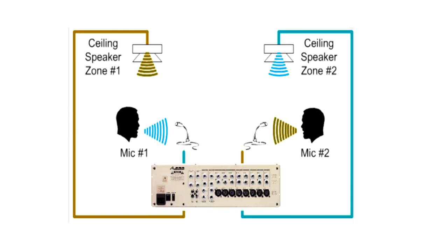But they have a microphone right next to them. Well, you don't want the audio from that speaker going to that microphone causing feedback. And so for that person that's sitting at a location with a microphone right next to a speaker, you would do something called a mix minus. What a mix minus would be in that case would be the entire mix that's coming off the board minus the microphone that they are talking into. So there's no direct feedback loop from that microphone to that signal.